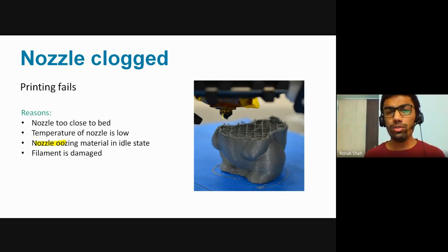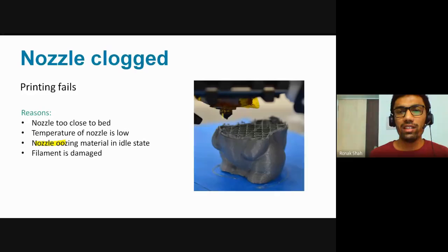And another issue is that the filament got damaged. Whenever the filament is pulled through the extruder gears, because of high printing speeds, the extruder gears put impressions on the filament and change the diameter of the filament, and because of this the filament is getting damaged, and this damaged filament gets deposited inside the nozzle, and that causes the blocking of the filament.